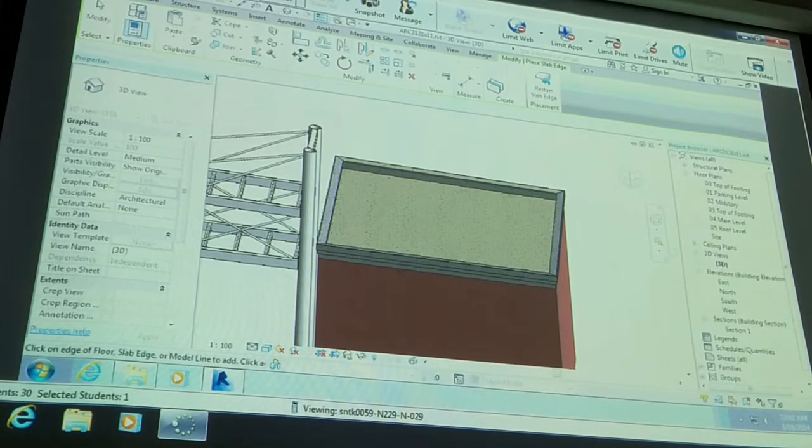Well, you see, there's an architectural roof tool. There's no structural roof tool. So I think it's not unusual to have an architectural column and a structural column in the same location. So you could do a structural floor, which is your structural slab. You could also have an architectural roof in the same location. Your roof hatch would go into the architectural roof. You would have to make an opening in the structural floor in the same location.